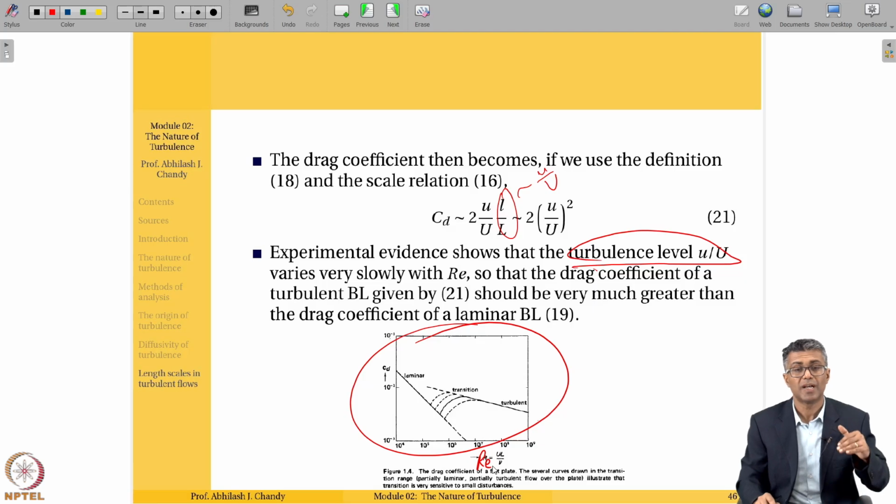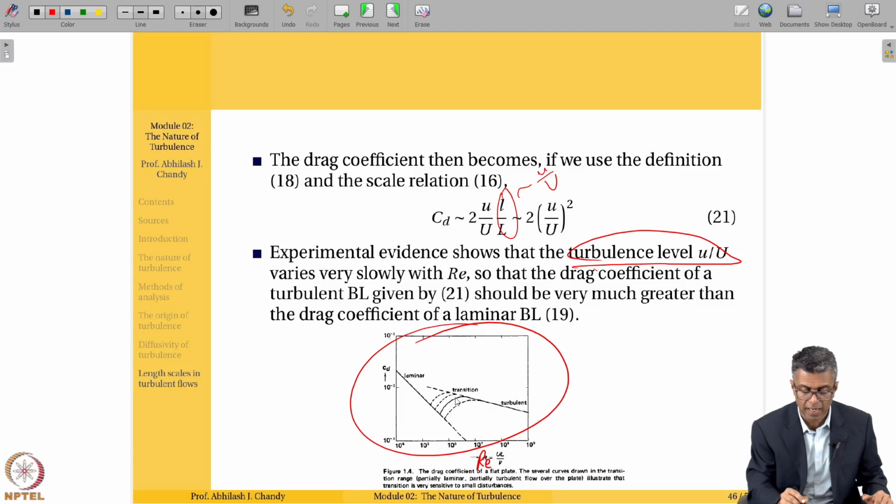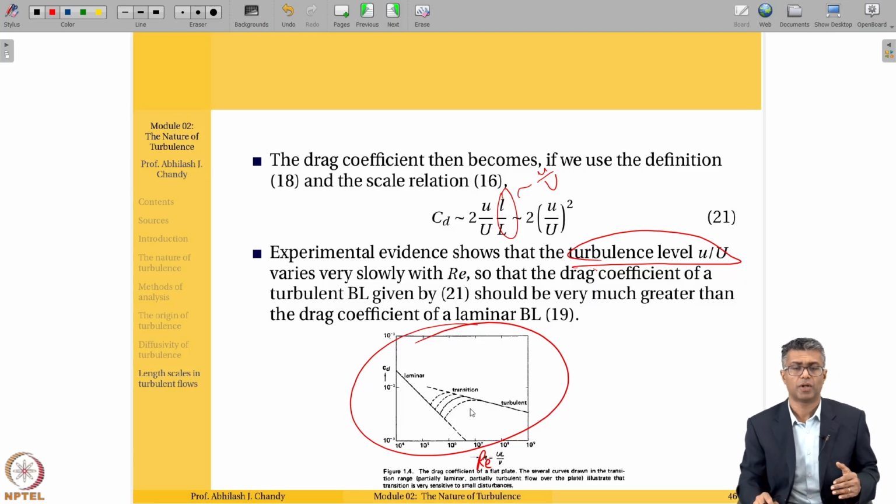With laminar flow, there's a significant dip in drag coefficient as the Reynolds number increases. As long as the flow is laminar, you see this huge slope. And then as it is transitioning to turbulence, you see this line that the slope is much lesser than what you would have in a laminar flow as the Reynolds number increases. I'm talking CD versus Re.